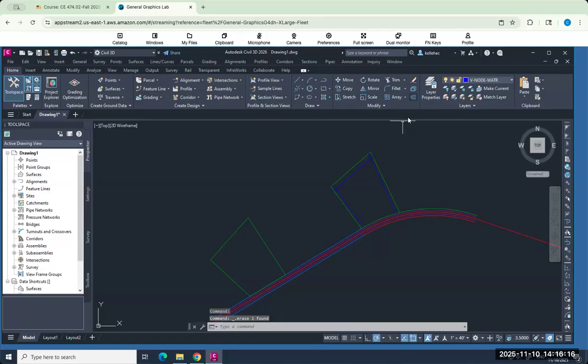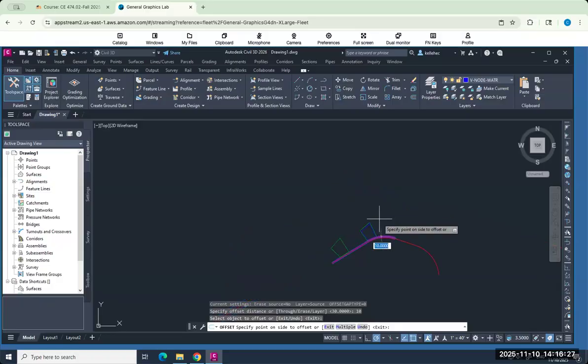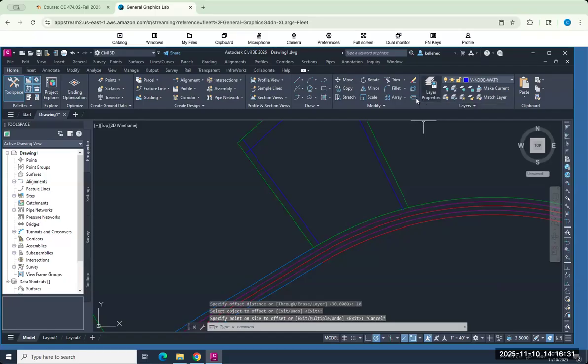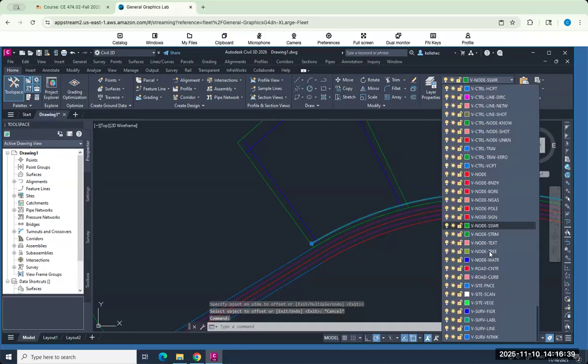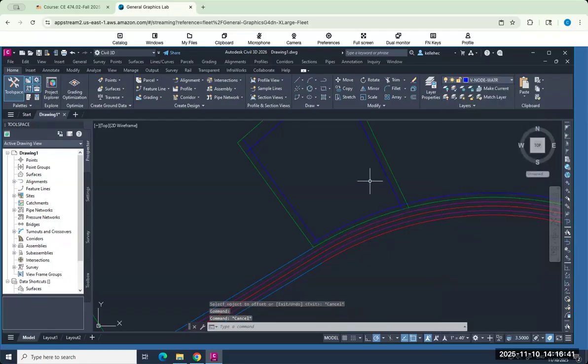Another alternative, so again here, I want to offset this, maybe my build-to line is 10 feet back. Whatever it is, you're going to use that guidance. So, oops, I'm zooming in here. I want offset, I want 10 feet. I'm clicking this line and I'm offsetting up. I want to move this to that other layer.